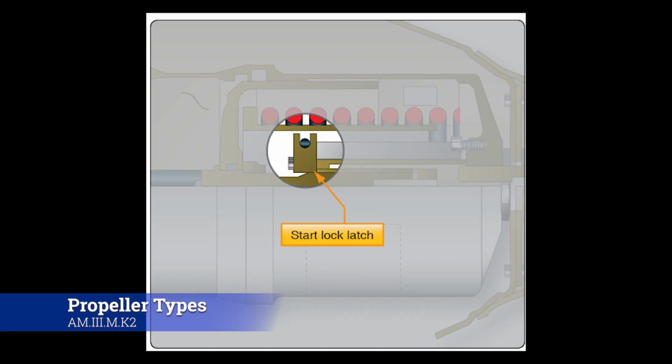Now, think about this. If you have a Baron and you're flying along, you have two engines, one on each side. If all of a sudden one engine fails, and now that prop, instead of producing thrust, starts to produce a large amount of drag, it's going to make that plane want to yaw pretty significantly. If it yaws significantly, you can get to the situation where it's almost impossible to operate, and you end up crashing because of it. By allowing that prop to feather, you get rid of that whole thing. It'll still want to yaw because the prop's still out there catching the air, but it's not going to do it nearly as much because the blades are laid flat rather than being vertical, catching every bit of air that comes across.